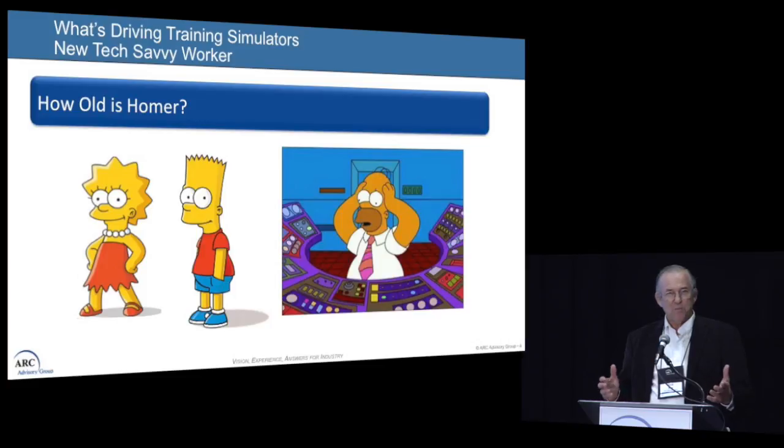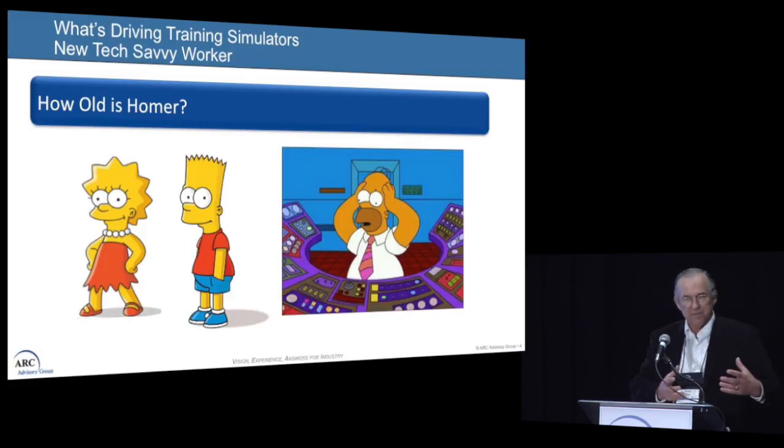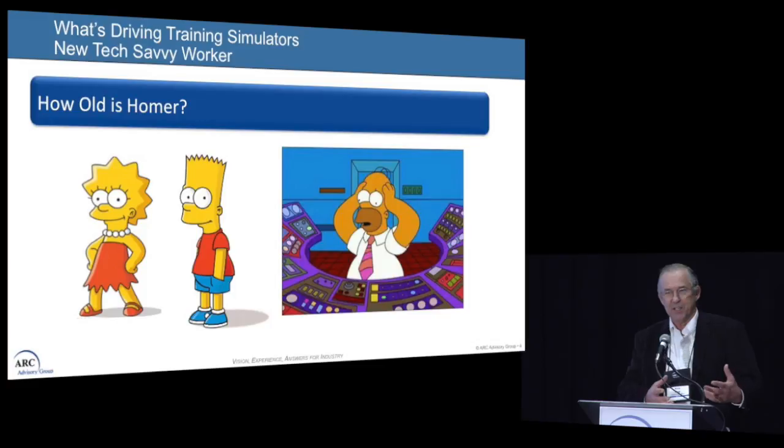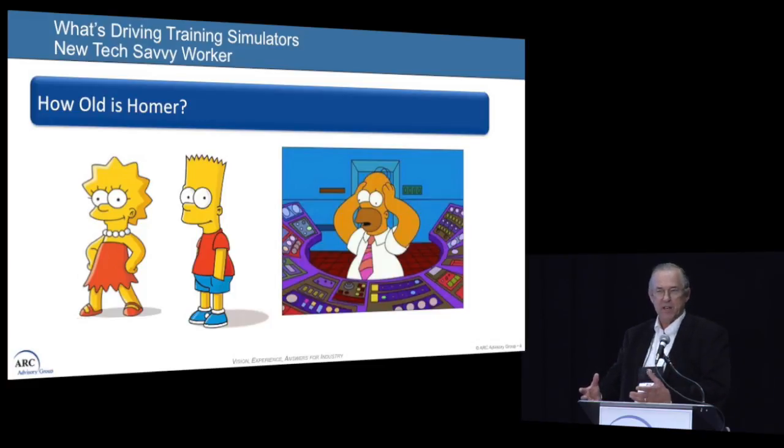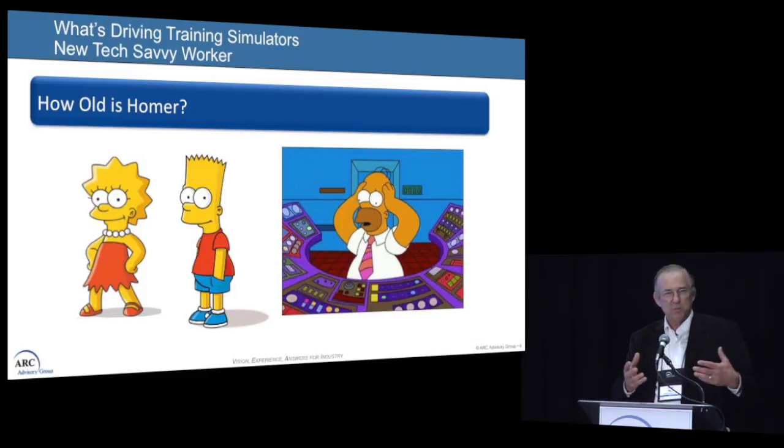The most successful programs that made an operator effective were those where people spent a lot of time in the control room, walking out in the field to see what the operator does, and to see whatever tools you gave that operator, how the operator actually used them. You have to treat your operator as your customer, right? Your operator is your customer. Your customer needs the right information at the right time, presented in the right way.